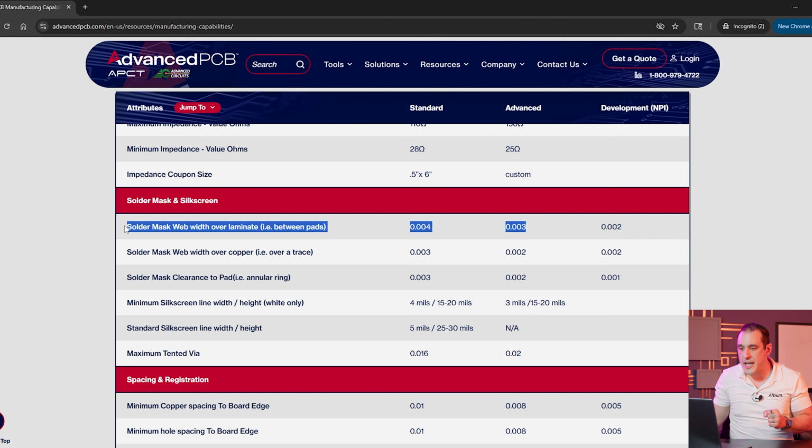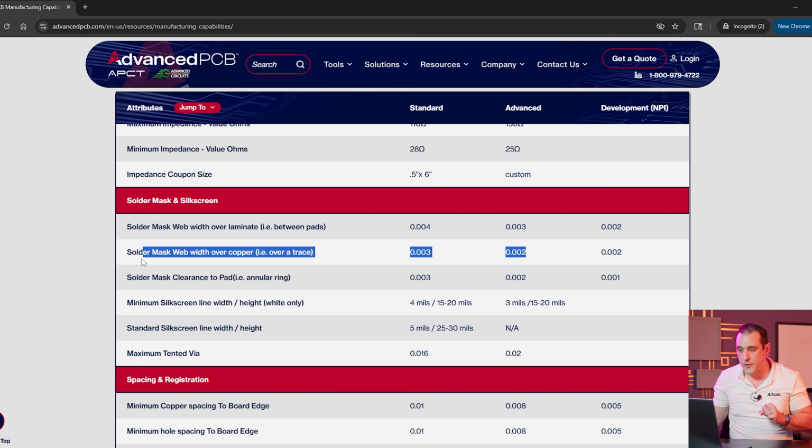Now, this first line gets entered into the solder mask sliver value inside your design rules. This is a little more difficult because it's both a sliver value, but also a solder mask covering value. So it's a little bit different. And there really isn't a way to distinguish between non-solder mask defined pads and solder mask defined pads in the design rules. So this is something that you set up in your BGA footprint, and once you set it up, you're just going to have to leave it based on the via pad size that you're going to be using to do your fan out.